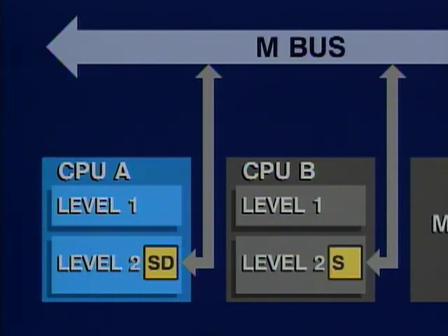If the tag field has the shared bit asserted, indicating that the data is present in one or more other caches, the CVAX will generate a write-through cache transaction to the MBus. Any other Level 2 cache that shares the location will invalidate its entry.